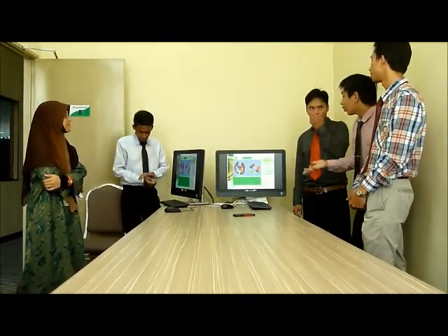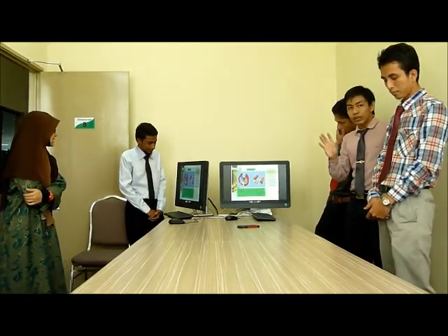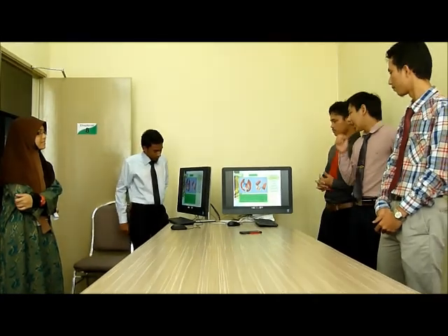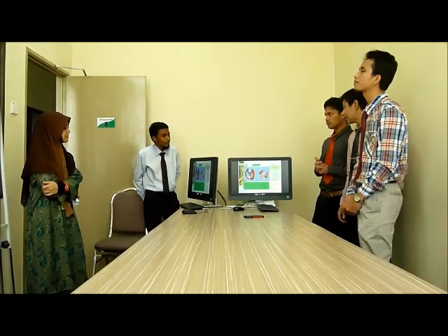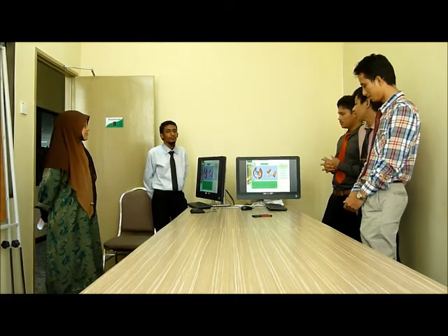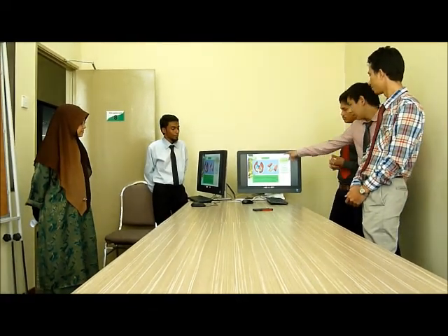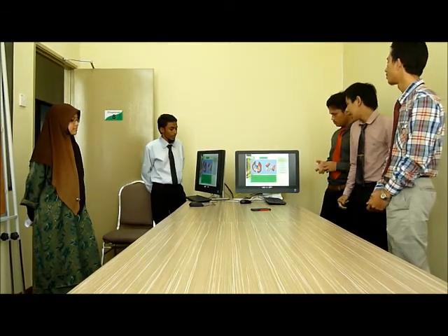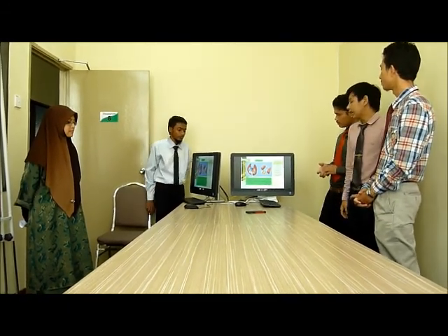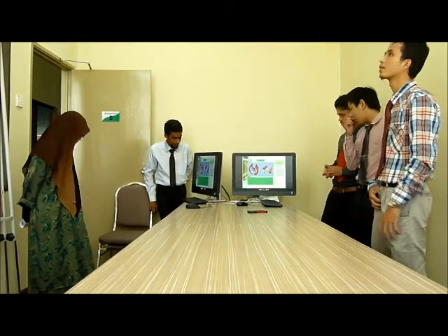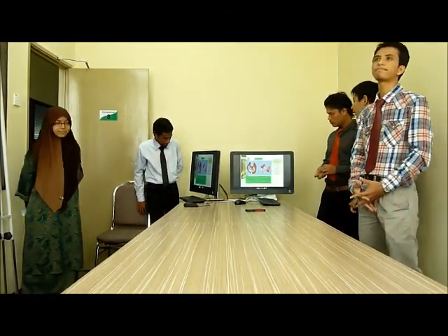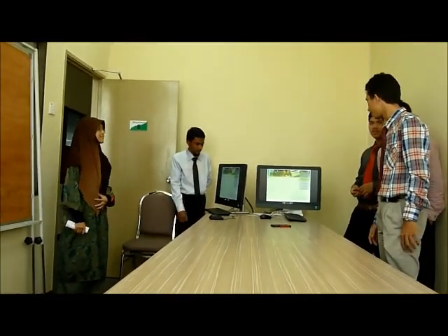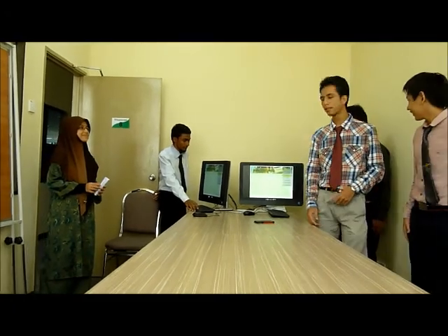Now when the coil turns through 180 degrees, the sides get interchanged. As a result, the commutator ring C1 is now in contact with brush B2, as we can see in the diagram, and the commutator ring C2 is in contact with brush B1. Therefore, the current continues to flow in the same direction. Now I will pass to the parts of the DC motor. Thank you.